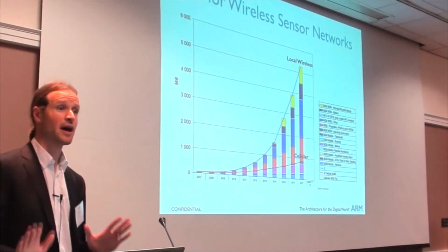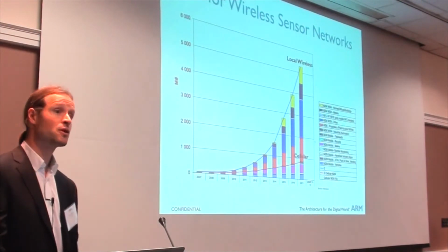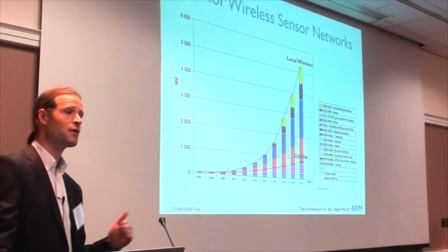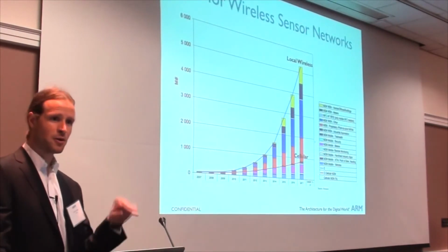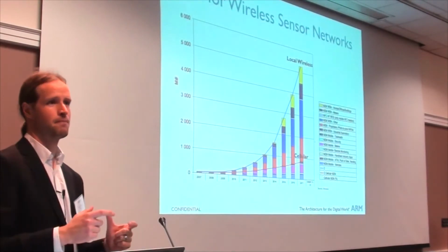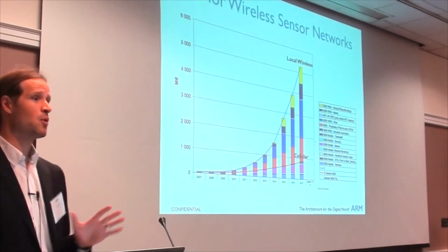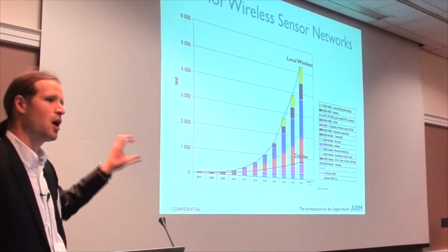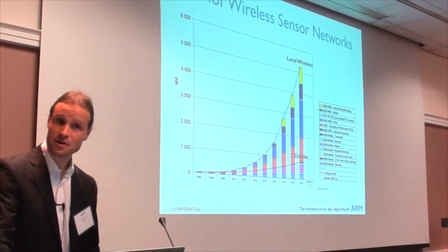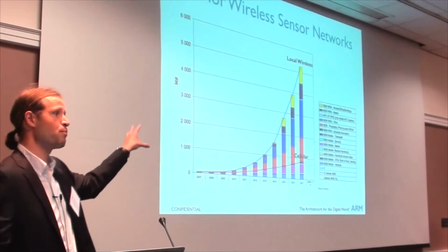One example is street lighting. The street lighting systems that we provide, we're providing most of the software for some major global players in street lighting. The ratios that these guys are aiming at, it's 500 to 1. 500 802.15.4G 6-LoWPAN lights behind a single cellular router. That tells us that we need to get in the business of IoT, not just M2M. So we need to provide services all the way down to those cellular plus sensor network devices. We need to manage them, do security, provide services, because that's where the big growth and potential revenue is.